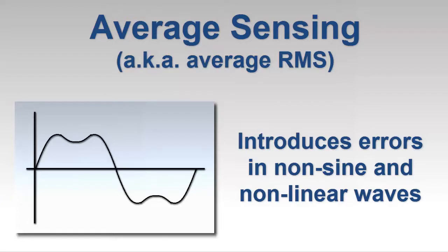The equation can also be problematic when an AC waveform is nonlinear, as would be found in systems where the original or fundamental waveform is distorted by one or more harmonic waveforms. In these cases, we need to apply a method known as true RMS.